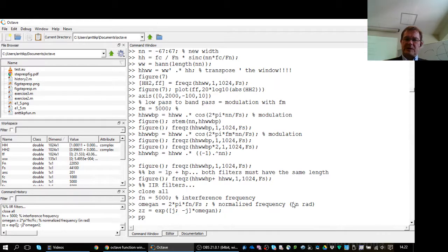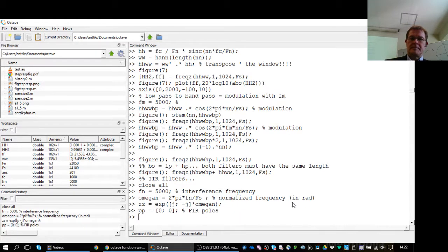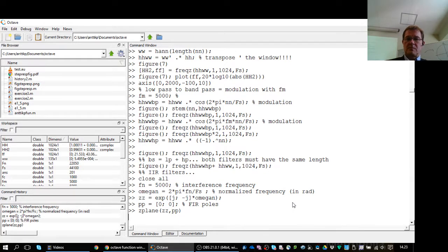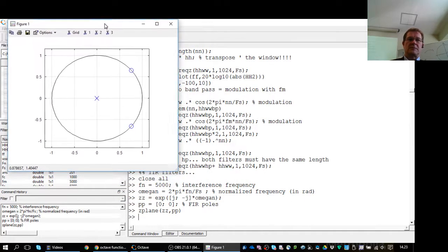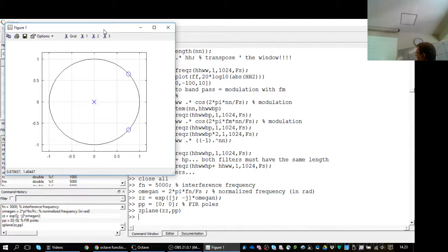And now we can even plot these zeros. But let me put poles also for a moment. So that's just currently in the origo. So this would actually define a FIR system. Since we need, in addition to zeros, we also need the poles. And then the Z-plane, zplane. Ha! There you are. So those are the locations of the poles. How come they are so close to that picture? Beats me. And by the way, the center pole is a double pole. It just doesn't show it.